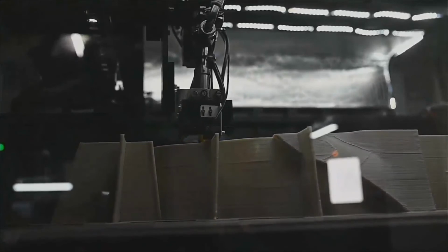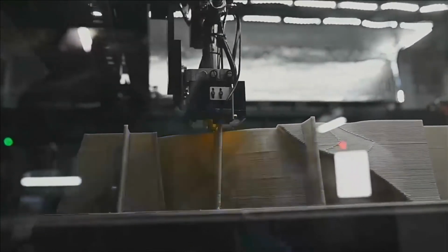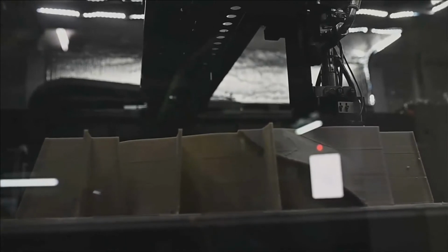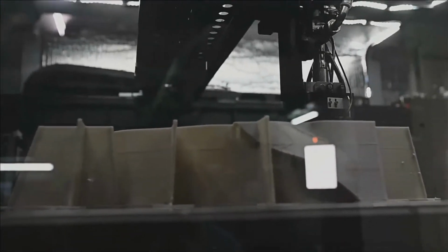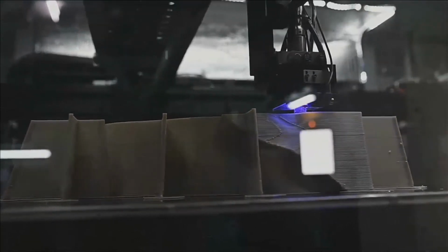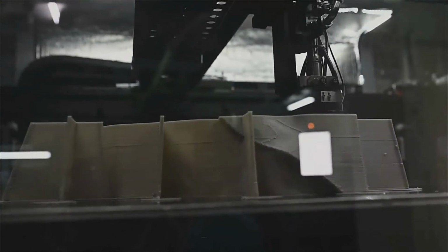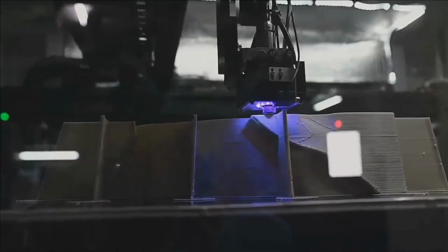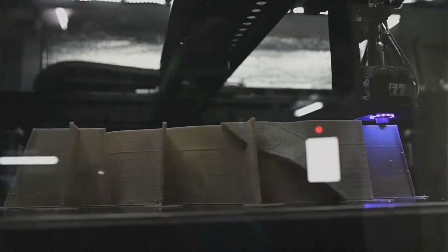We call the process cast in motion, as we cast as we print. Okay. First of all, we will print a few layers, and then we will cast the epoxy. The reason we do it has to do with the exothermic behavior of the epoxy. It is, of course, impossible to cast a huge amount of epoxy in order to be able to control the temperature of the geometry, the temperature in the printing area.